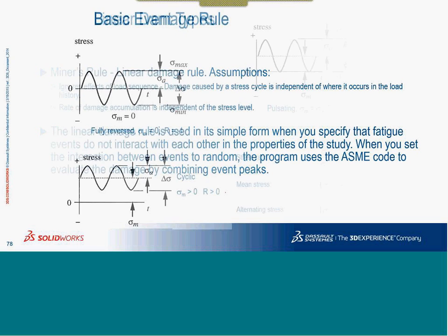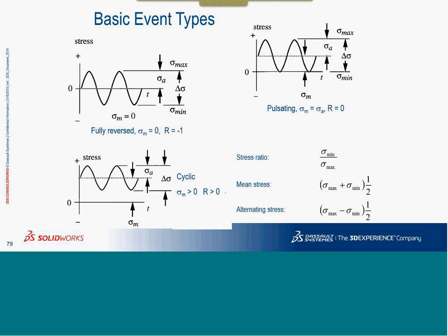In terms of stresses, when we apply the loads, we have a few different options over here. One is called fully reversed stress. Typically, the stress that we are taking from a static analysis is the sigma max. Here on, we are saying it is fully reversed. That is, it is expected to go completely in the other direction. That is, if it is plus 10, this can go all the way to minus 10.